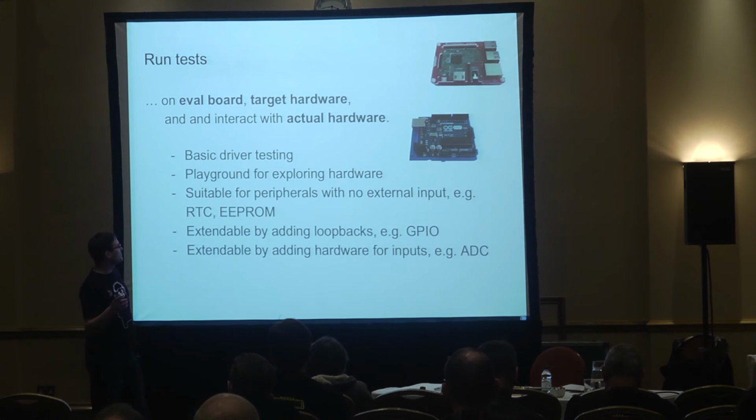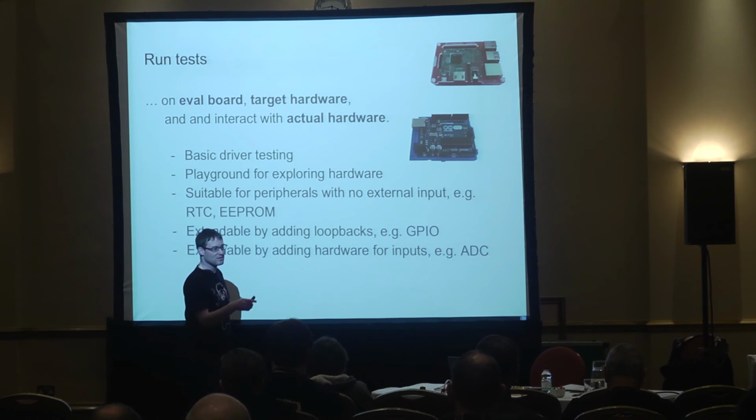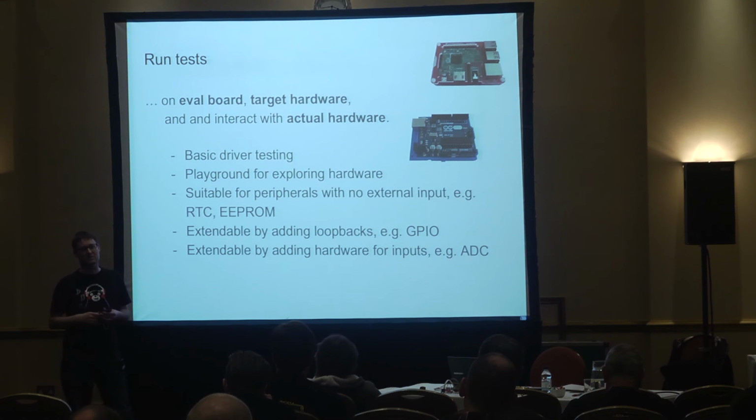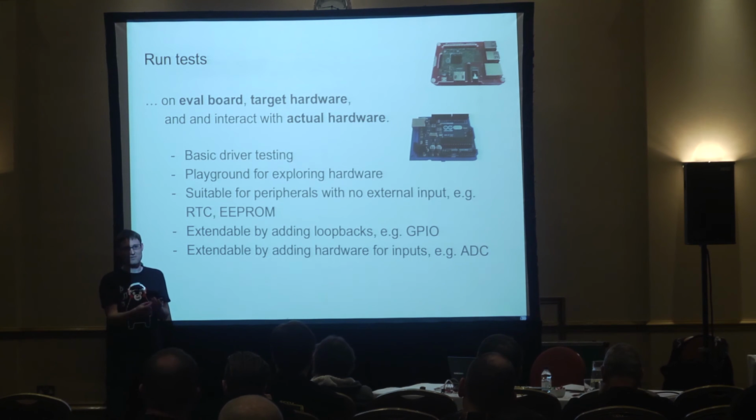What you can also try to do, that's an example for that, is you could make special unit tests for your target, where you try to interact with the hardware. Now, if you have some hardware device, for example, an EEPROM or an RTC, you can really write a unit test that communicates with it, and you're not depending on input from the outside.